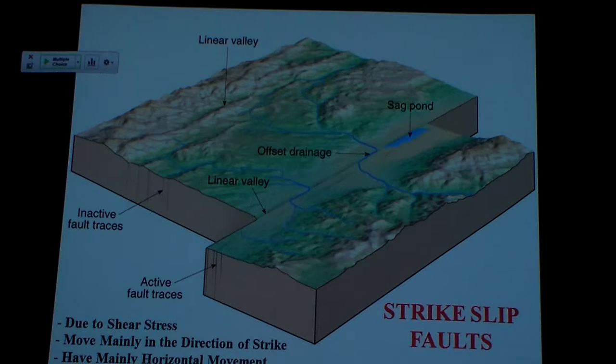Okay, so we've been talking about dip-slip faults, moving along that angle. What if instead of moving that direction, they move along strike? Now I'm just moving laterally, side to side, along that compass bearing that we took. And as you might guess, we call these strike-slip faults.